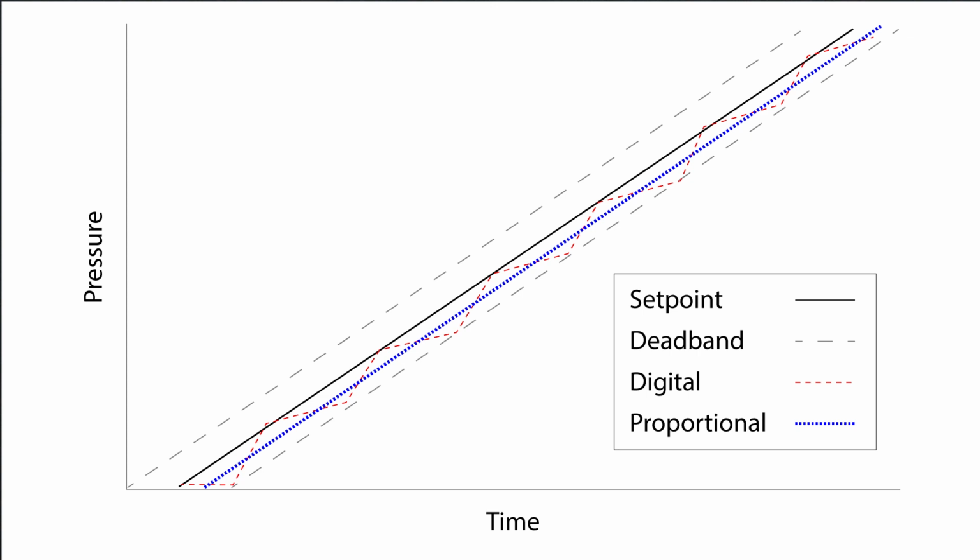Something else to mention is hysteresis. For our purposes, it is the difference in result when approaching the set point from two different directions. Hysteresis can be a result of the control scheme used or deliberately added to prevent the unit from hunting around the set point. Our illustration shows the hysteresis of this setup as two gray lines. If the hysteresis is deliberately added to the system, it is often called a deadband. Feedback changes within the deadband do not result in a controller action.